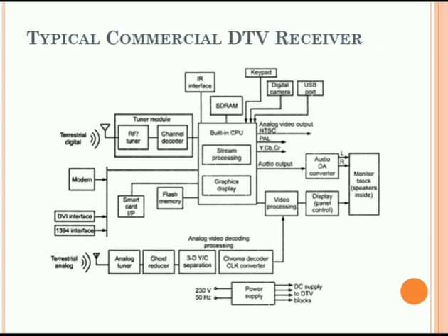The compressed audio bit stream is given to the audio decompressor unit, and audio decompression is achieved using the MPEG-1 audio decompressor unit. The decompressed digital audio data bit stream is given to the audio DAC for D2A conversion purpose. Finally, the processed audio signal is given to the speaker system, where the audio information is reproduced. System clock and sequencing control is essential because the entire bit stream is being processed digitally. Hence, for the purpose of synchronization, we are using the system clock and sequencing control unit.